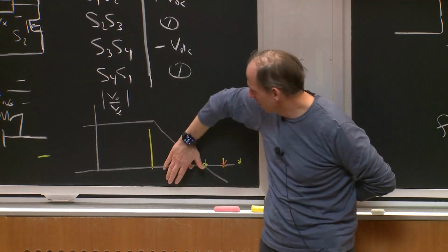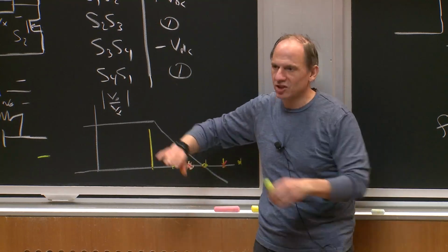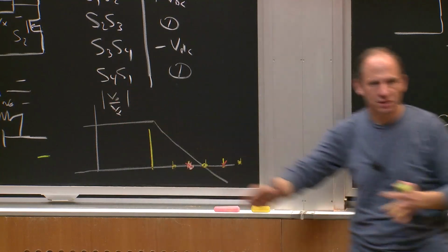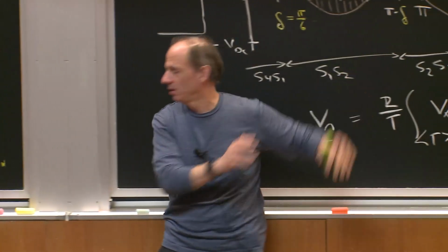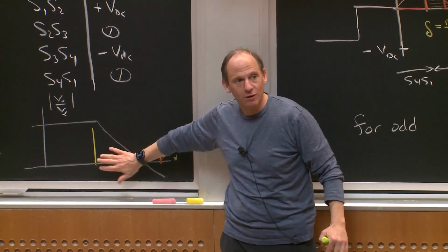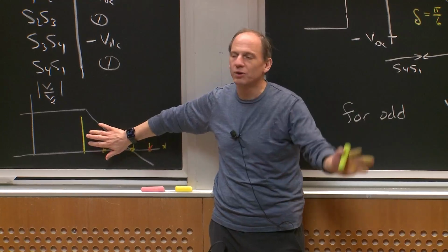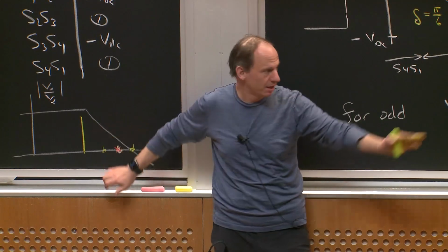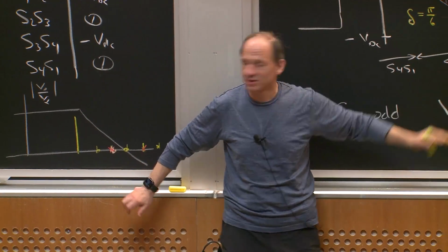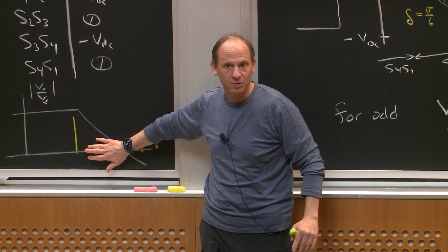It's hard for me to eliminate stuff that's near cutoff. So I'm pushing the frequency content up and keeping the stuff that's hard to filter low. Okay, so I'm not getting rid of high frequency content, I'm actually increasing it. But what I am getting rid of is the stuff that's hardest to filter. Okay, any questions about that?